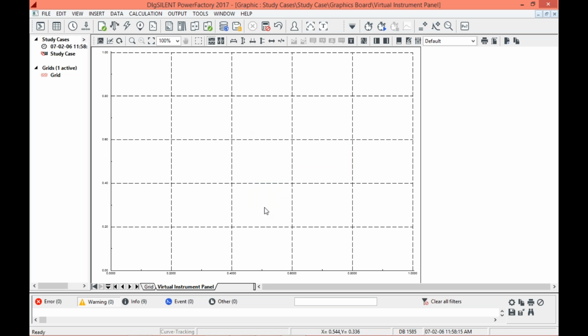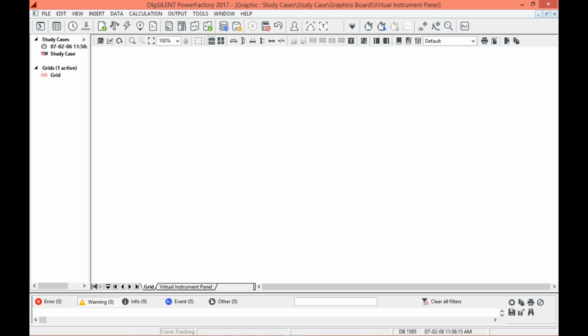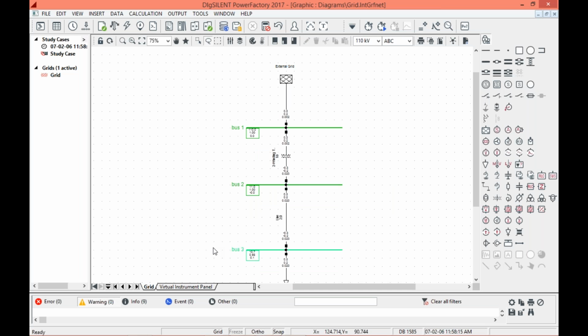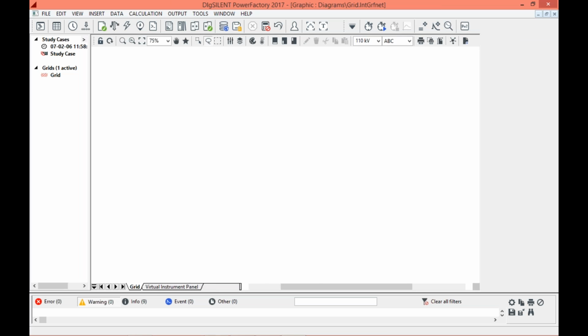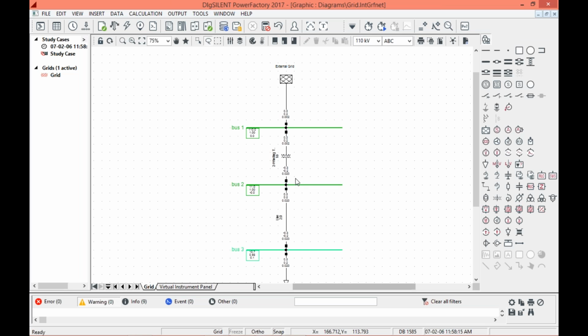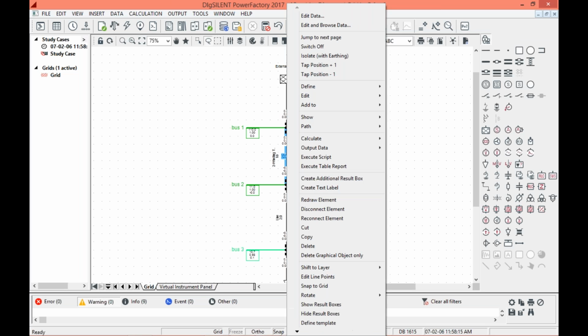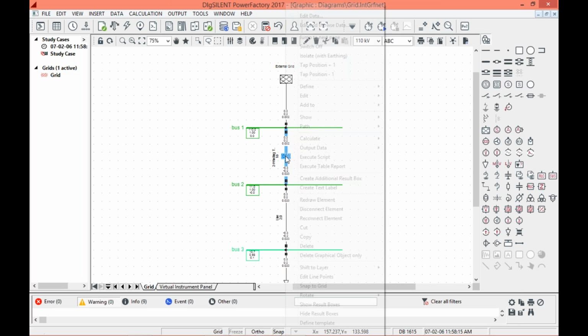As the subplot gets introduced, the next thing you have to do is define the power system elements. Defining the power system elements is needed because, as I was showing in the presentation, when you define those components they will show with their appropriate colors, but here it is totally blank. It means no element has been defined yet. So what we will define is the two winding transformer. Click on two winding transformer, it will turn blue.